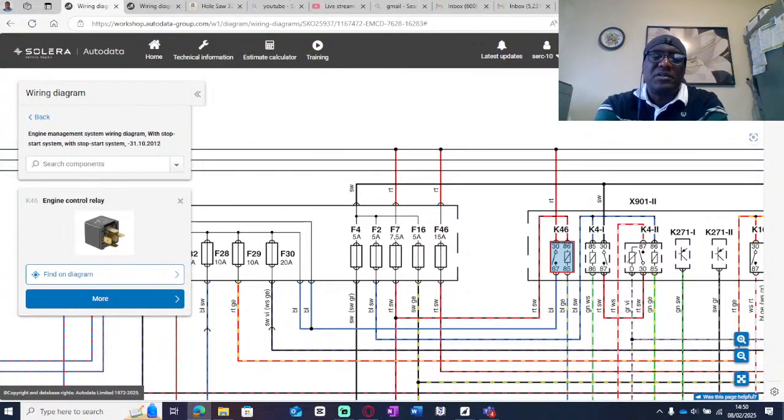So you're going to find that these GDI engines have better thermal efficiency as compared to the port injection ones. And high pressure as well. They do use high pressure. The injector that they use is totally different. It's not a high resistance injector. You find that it would be maybe just 1 ohm or 3 ohms or something like that. Now it's different from the other injectors that would be 14, 16 ohms like that. Okay, yeah, I can talk about that one at some stage.